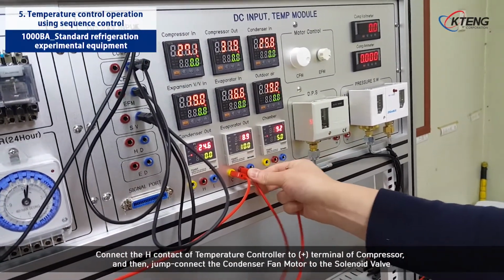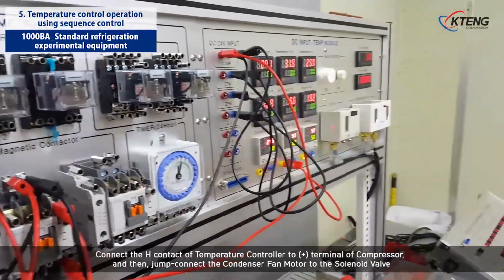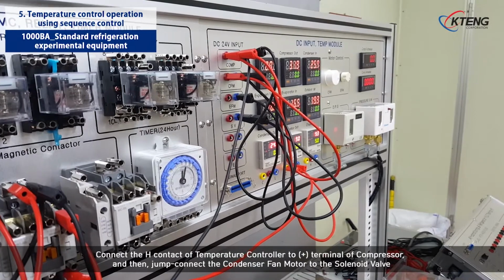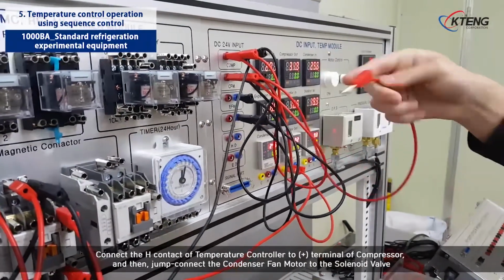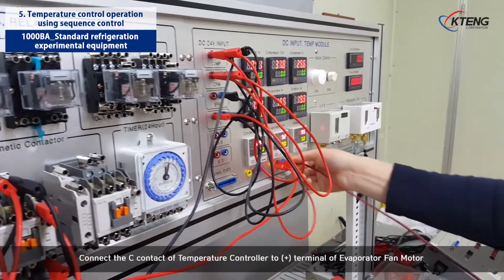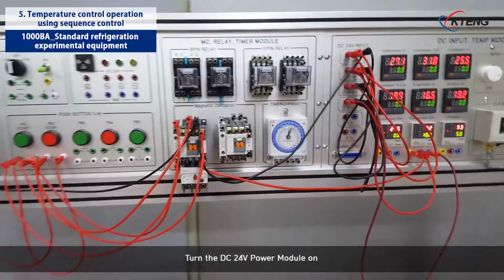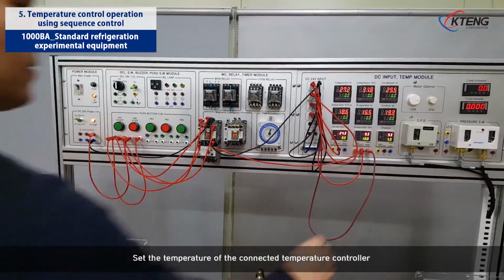Connect the H contact of temperature controller to the positive terminal of compressor, and then jump connect the condenser fan motor to the solenoid valve. Connect the C contact of temperature controller to the positive terminal of evaporator fan motor. Turn the DC 24-volt power module on. Set the temperature of the connected temperature controller.